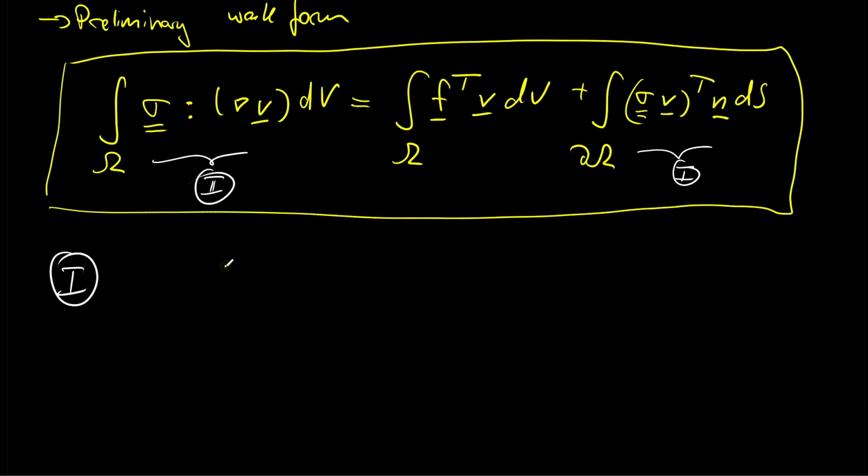So let's first make some changes here. For this, I will write that expression down once again. So we have the sigma matrix vector multiplied with the test function, and then transpose with the unit normal vector. Let's make some linear algebra modifications. So let's apply the transpose to that equation, which reverses the order and applies the transpose to both parts, which gives us v transpose sigma transpose n.